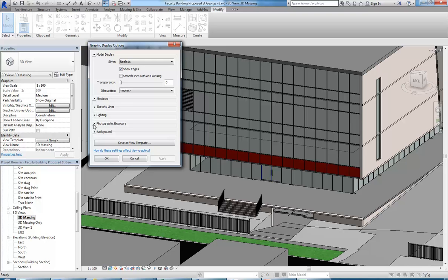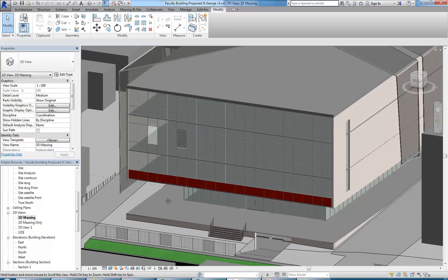So without rendering, you can have lighting showing, even interior lights that aren't rendered, and do some really interesting things graphically. And shadows, you can control the shadows in some interesting ways, and do a lot of things that you might think you need to use Photoshop for. Just shadow and Revit, and it's all set up for you. Backgrounds as well, so lots of interesting things you can do there. Yeah, we'll look at that after the break.